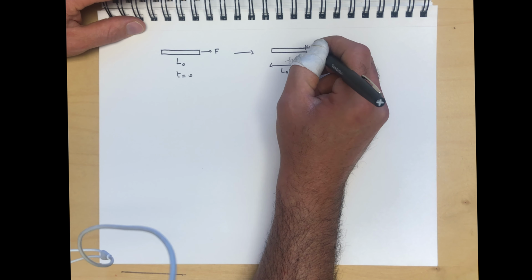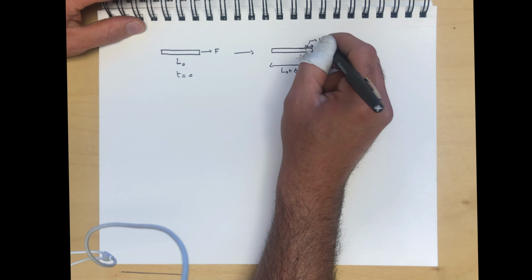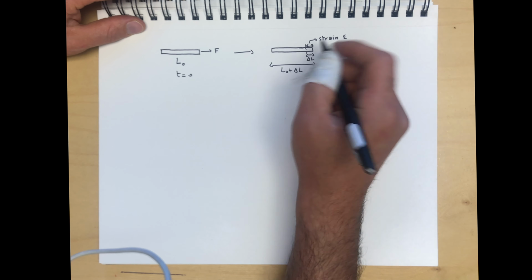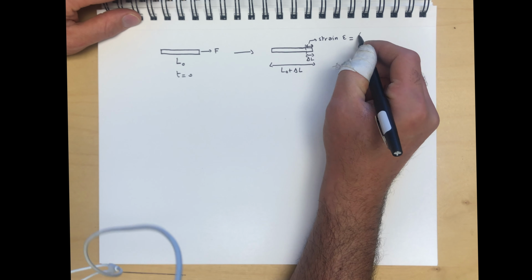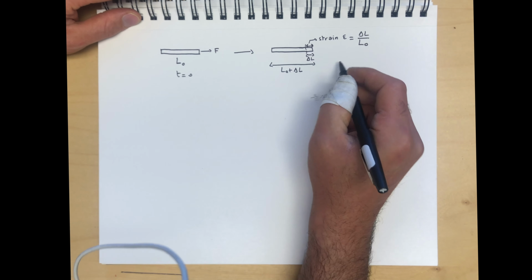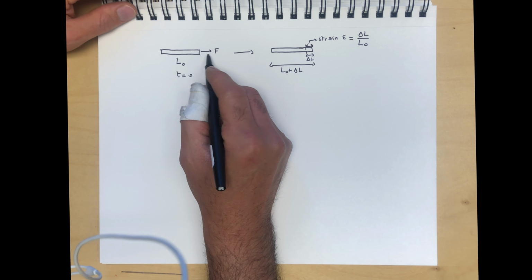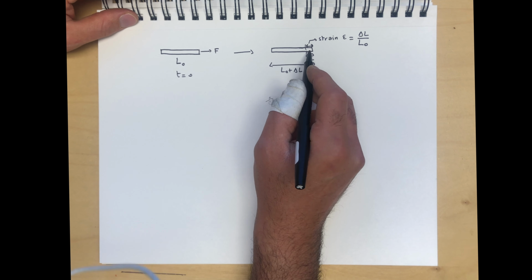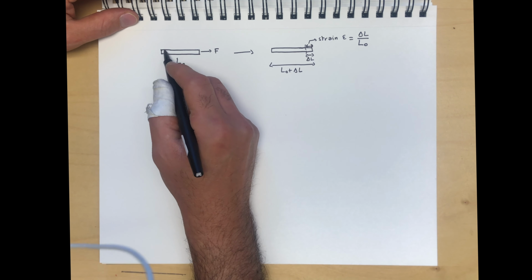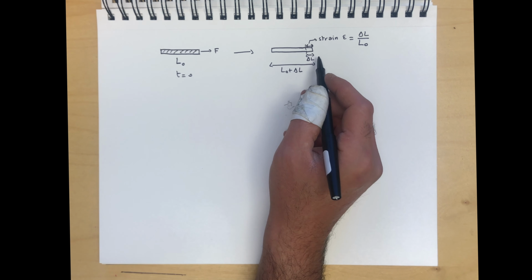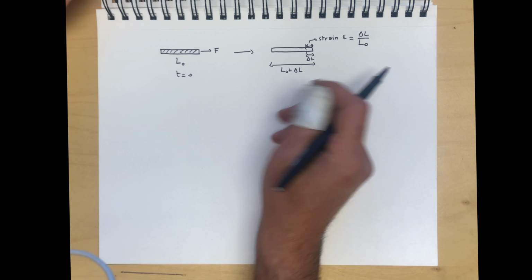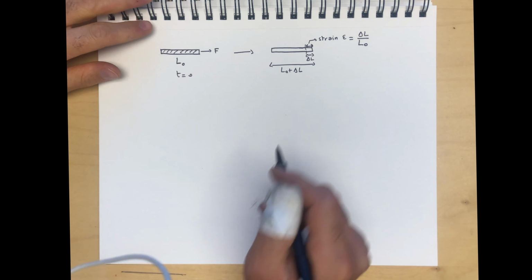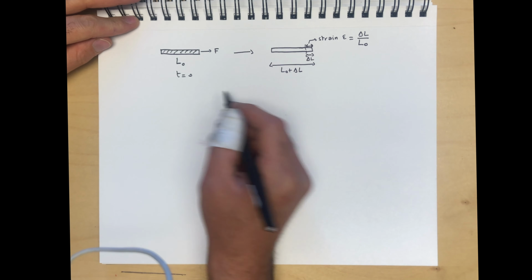And this displacement is called strain. Okay? Strain, we're going to call this epsilon. And, well, the normalized strain is epsilon. More specifically, that's delta L over L0. And obviously the force and the strain are related, because the higher the force, the more displacement there will be. And depending on the material, the displacement may be different. You could have a very strong material that you can barely pull, or if you pull it, it may behave in a nonlinear fashion.